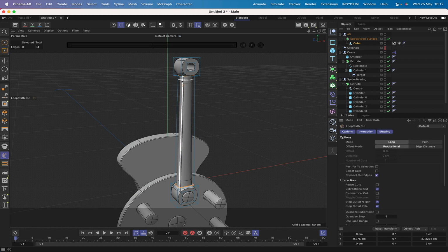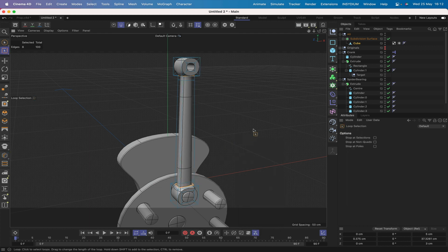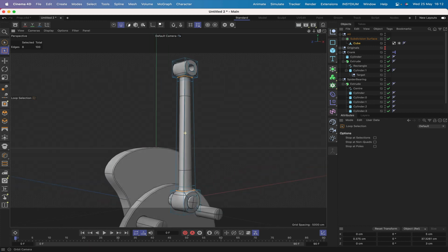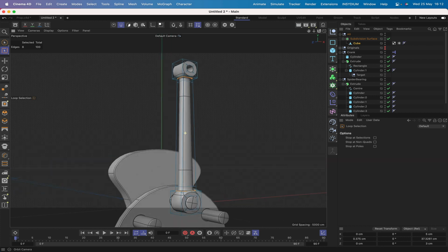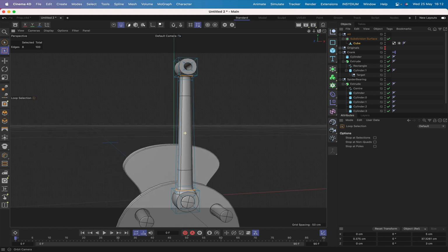KL for a knife cut there, it's a loop cut. If we just do this probably there, and we do this one just here, that's quite nice. And then once again I can do UL, and we can hold down the full stop key and just relax those a little bit more, and it just gives it that sort of subtlety down at the bottom and at the top, which I really like. It's a nice effect, that is. That looks really nice now.